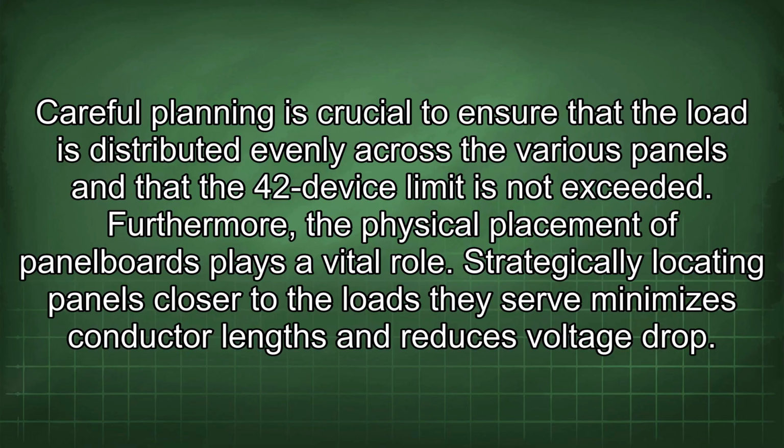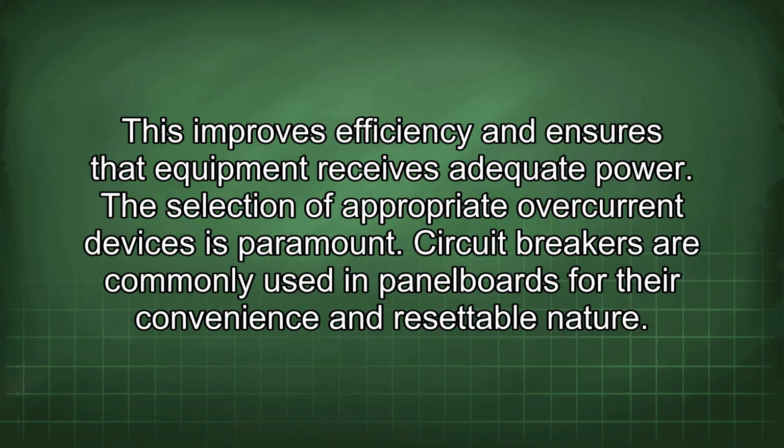Furthermore, the physical placement of panel boards plays a vital role. Strategically locating panels closer to the loads they serve minimizes conductor lengths and reduces voltage drop. This improves efficiency and ensures that equipment receives adequate power.